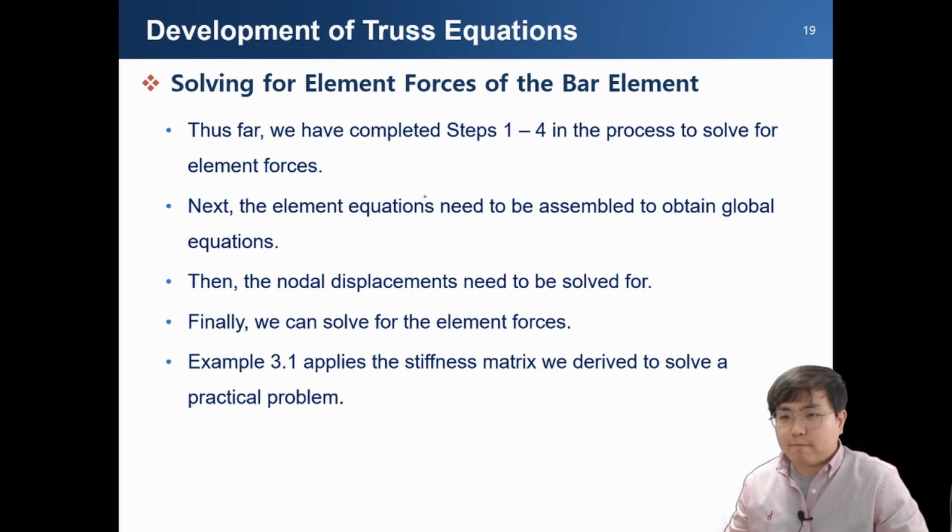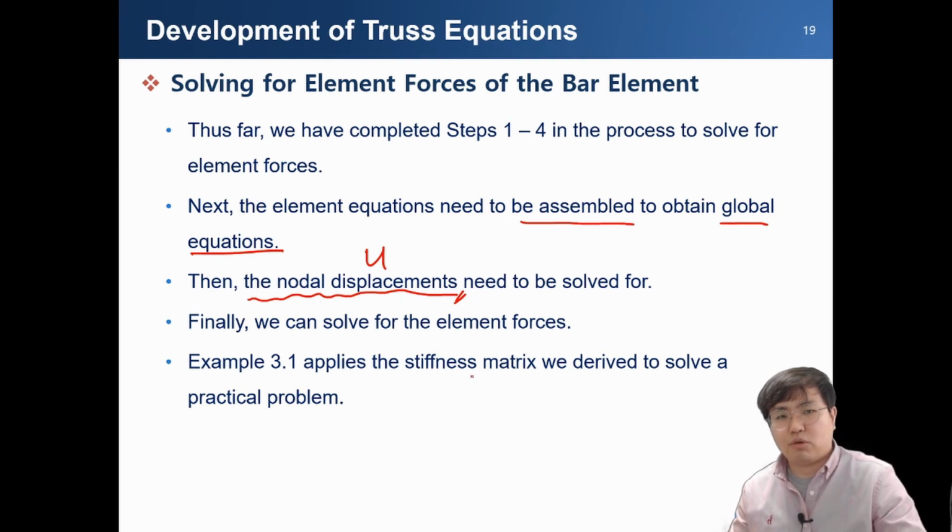With those methods, we can obtain the local stiffness matrix of the truss system. However, after obtaining the local stiffness matrix, we should assemble it into the global stiffness matrix. Our final goal is to know the nodal displacements. To obtain these variables, we should apply some boundary conditions depending on your system. Without knowing the boundary conditions, we cannot solve it. So, what is the boundary condition?